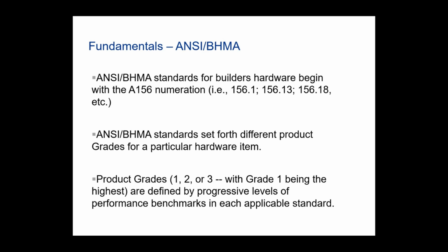There are some manufacturers out there that, whenever you're talking usage, Allegion, I'm just going to say broad manufacturers, Allegion has a cylindrical lock set that I believe is at about 5 million cycles. You have another one from Sargent that is about 3 million cycles.